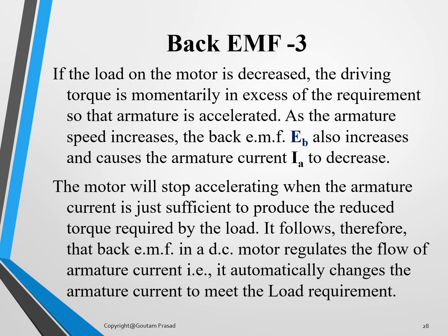More flux will be cut by the conductor and back EMF will be more. If the back EMF is more, the armature current IA will decrease. I am explaining this to show how the DC motor becomes self-regulating with the help of back EMF. Back EMF makes the DC motor self-regulating in nature, and this is very important for electrical engineers to understand, my friends.